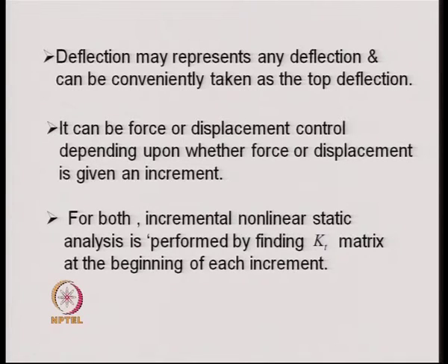Now, the pushover analysis can be force or displacement control depending upon whether we increment the force or increment the displacement. So, what we do is that either we gradually increase the displacement in the structure and look into the behavior of the structure, or we increment the force and then we study the behavior of the structure.